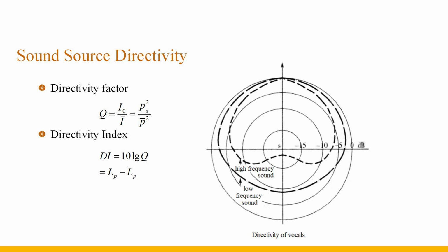There are two main ways to express the sound source directivity. One is the directivity index, taking the sound pressure field formed by a non-directional point sound source with the same sound power as the reference value. The difference between the actual sound pressure level and the reference sound pressure level in a certain direction at the same distance from the actual sound source is called the directivity index of this point, also in decibels. The distribution of Di is generally obtained through field measurements.